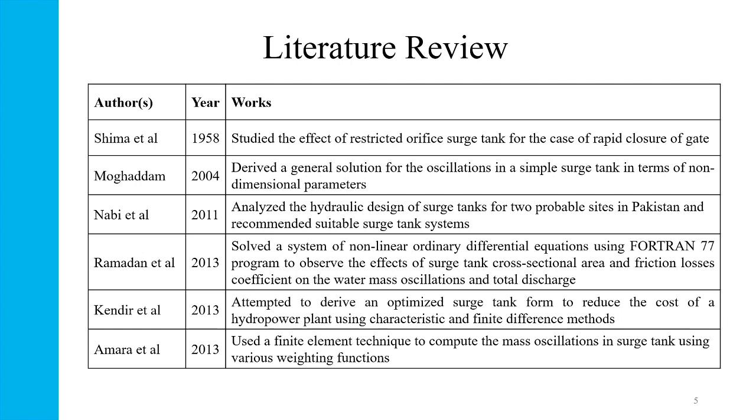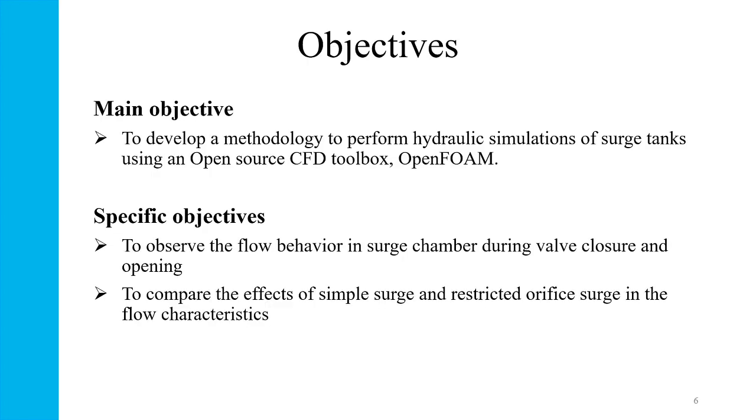From the literature study, it was found that a substantial amount of work has been done in the analytical calculations and numerical study of surge behavior in hydropower. A few studies have also been done with CFD analysis, particularly with commercial CFD codes like ANSYS CFX. Nepal, having an enormous potential for hydropower, has a lot of scope for the study of such surge tanks in different potential sites. Hence, the main objective of this study was to develop a methodology to perform hydraulic simulations of surge tank using an open source CFD toolbox, OpenFOAM. Also, our specific objectives included observing the flow behavior during valve closure and opening, and also comparing the differences between simple surge tank and restricted orifice surge tank using OpenFOAM.